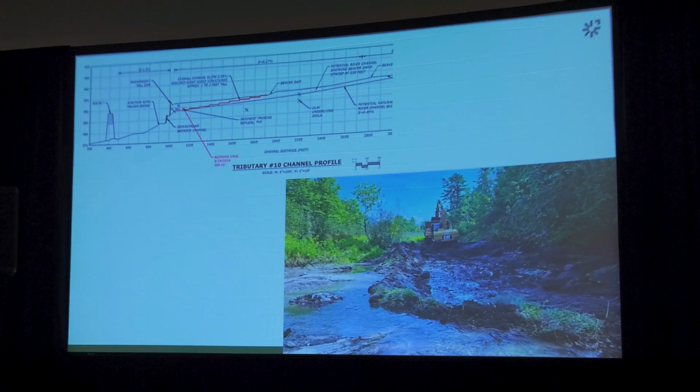So we had them excavate this out and survey it. And then we plotted that bedrock vein elevation on our profile and found it was half a foot higher than we expected in our design, which is perfect. We had to think through if we wanted to change any of the design cross sections moving upstream, and ultimately didn't, but it was a nice check.